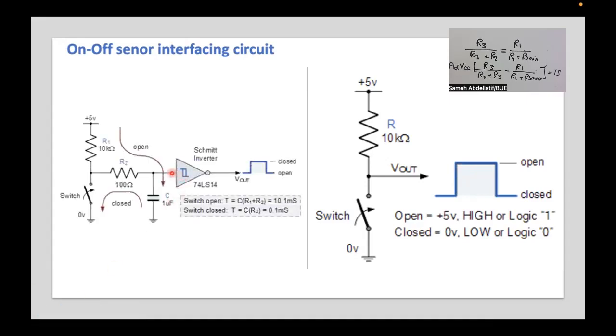we can use something like this. This is a modified circuit. Still we are using the same resistance branch with our on-off switch, as you can see, but here we add some sort of a filter. Whenever the switch is off, as you can see here, then you will have a current flowing in this direction, keeping this voltage high because it's connected over these two points. This is an open circuit, and the current will flow in this direction, making this voltage high.